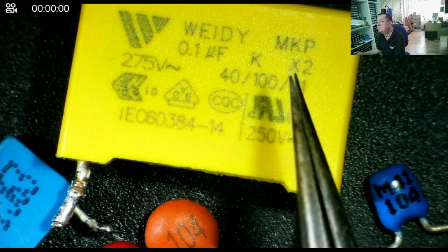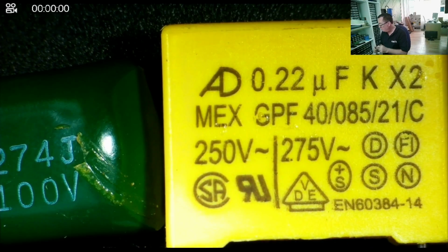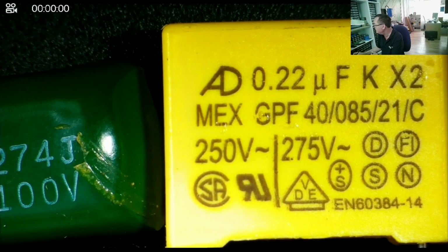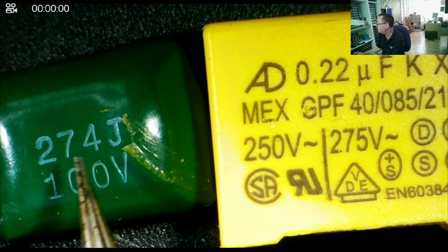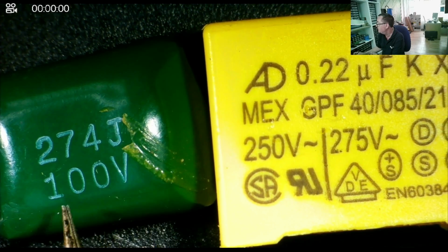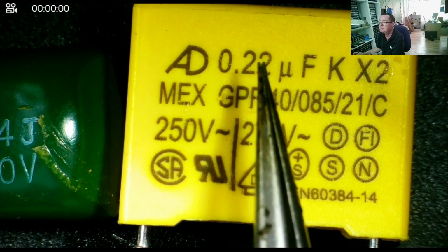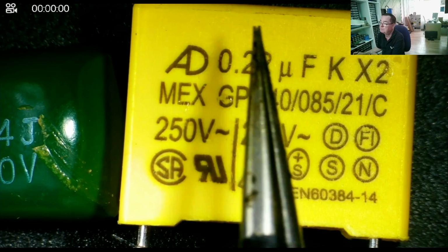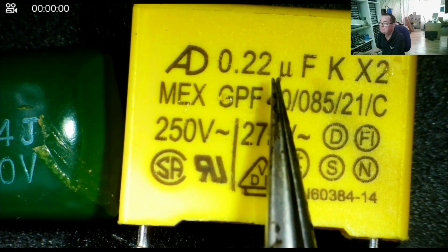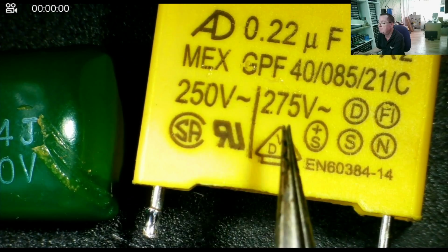This marking X2 is involved with this being a filter capacitor. While we're in this range, again 270 nanofarad, we've got a 220 nanofarad, so the same thing, 27 followed by 4 zeros, 270,000, tolerance. This has the voltage marked on this one, so you can see there are a number of variations. This one, 0.22 microfarads, could be marked, to be quite honest, as 220 nanofarads. It's the same thing. Again, the X2 marking, 250 volt AC.